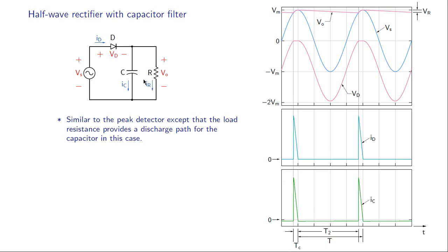Why is it small? Let's look at the circuit from the capacitor. What we see is this resistance and the diode resistance in parallel, and that is of course nearly equal to the R on of the diode, which is very tiny. Because the resistance seen by the capacitor is very small, the time constant for the charging process is very small, and as a result the output voltage follows the input voltage instantaneously, and that is what we see over here.